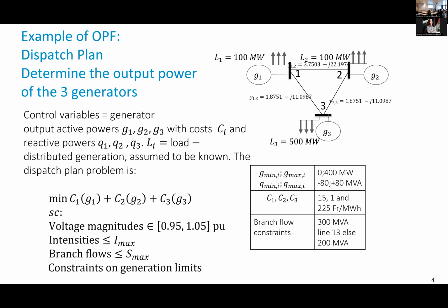Planning is done by markets and also by what are called the system operators, in Switzerland, Swissgrid, that has to decide at several time scales. But let's say, for example, every day, 1 hour before real time, Swissgrid has to decide what are the set points of all those generators. Swissgrid does not decide for every company how much they will generate, but lets the market decide first. We will discuss in 2 weeks how the market can come into play. And once the different actors have decided how much they think they will generate, then you typically need a few additional reserve generators that will make sure the system is completely balanced.